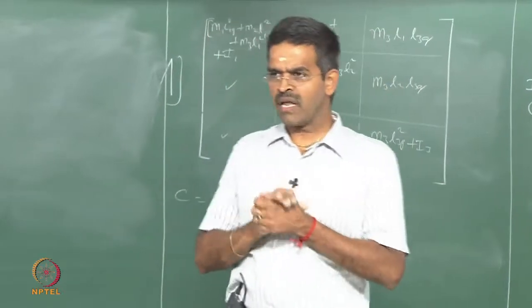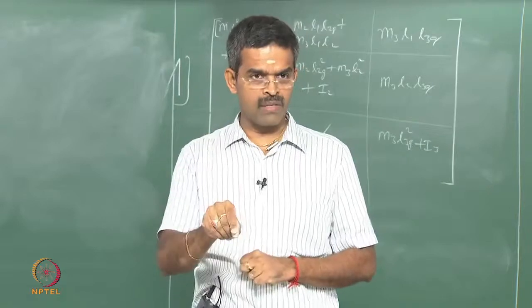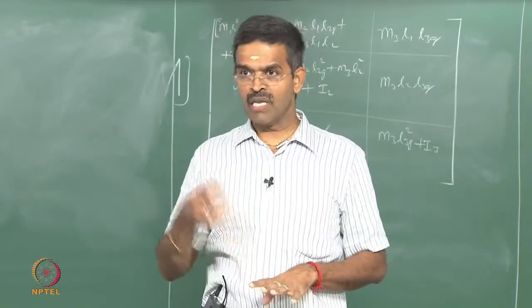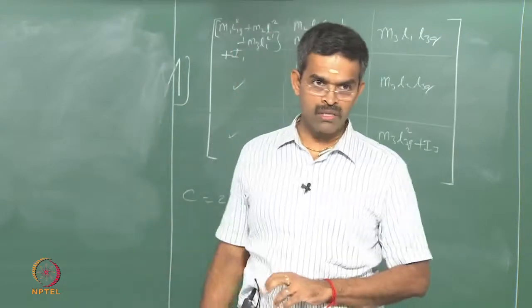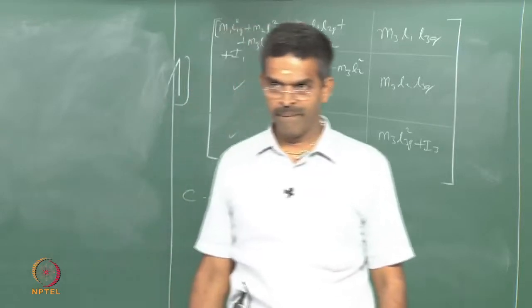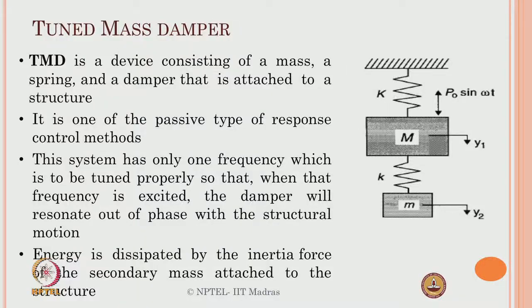So we generally take care of dampers in the system, like C equals 2 zeta omega m, we introduce damping in the system, 1%, 2%, 5%, etc., which are fortunately derived from hydrodynamic damping in offshore structural models, or one can also have external dampers, which I am going to apply in this system here. So the spring mass system of k, m, which I call a secondary mass system, is actually nothing but an additional damper to the primary system.